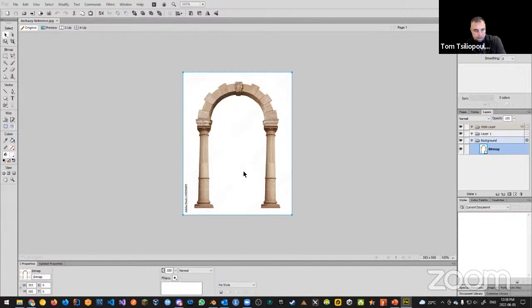Mithul says, add the reference image, add cylinders along the image, and mesh the archway. Yeah, we could do that. We could do all that kind of stuff. One thing to note is that we know that the archway is symmetrical. So we can split the archway in half. We know that. So we can start off with this. Kevin says, I'd add the image on the plane, use the blueprint, use cylinders for the column, and mirror the mesh. Good. That's exactly what I would do, right?